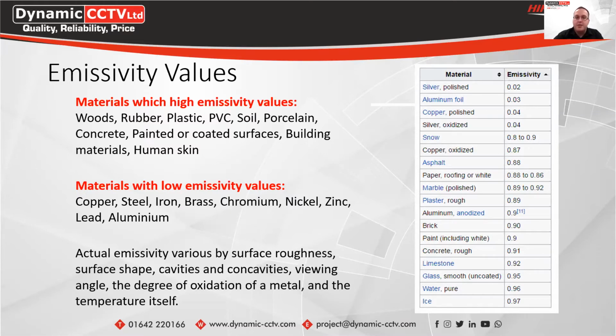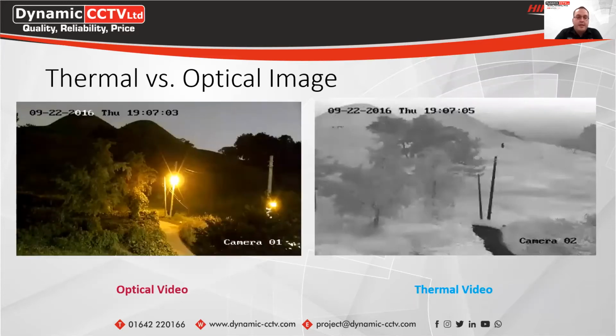Emissivity ratings are just a base level, but you should check them with a thermologist for the most accurate kind of setup with the thermal cameras, especially when needing high degrees of accuracy for temperature measurements and temperature differences. What we can see there is the differences between the optical and thermal images.